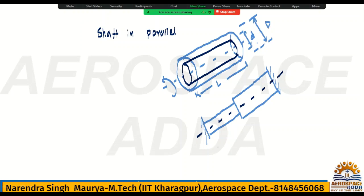Here you can say a torque is acting like this, and this torque is nothing but torque T. This end is fixed, and this is also fixed. So if you apply torque here, you will get a resisting torque at this end. Say this is A, this is B, and this is C. At end A you will get a resisting torque because it is fixed, so say at this end the torque is T1. This magnitude will not be equal to the applied torque because both ends are fixed. So don't say that whatever torque you apply at T will be the same at A. Not possible, because both ends are fixed.